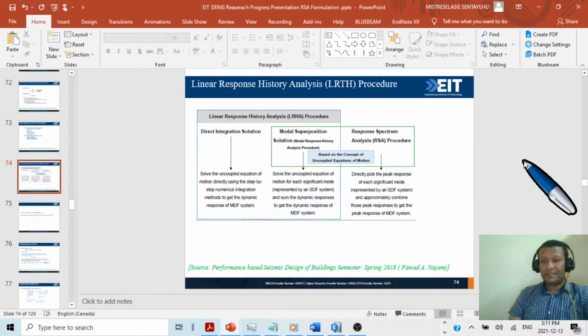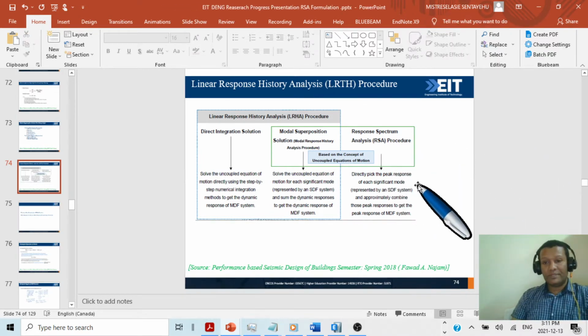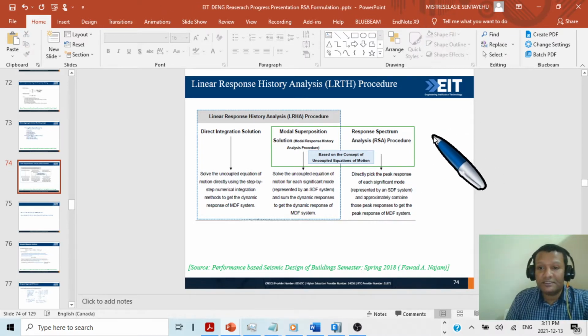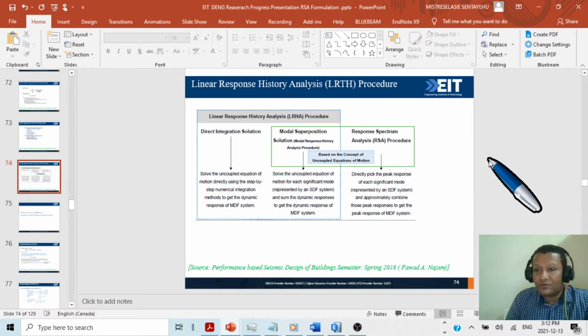This was also explained in my second video, but just to revise: for a single degree of freedom system with constant damping ratio xi, mass and stiffness k, we run our system for different periods and pick the maximum displacement for each period, for example 0.5, 1 second, 2 second, 2.5, 3 second.